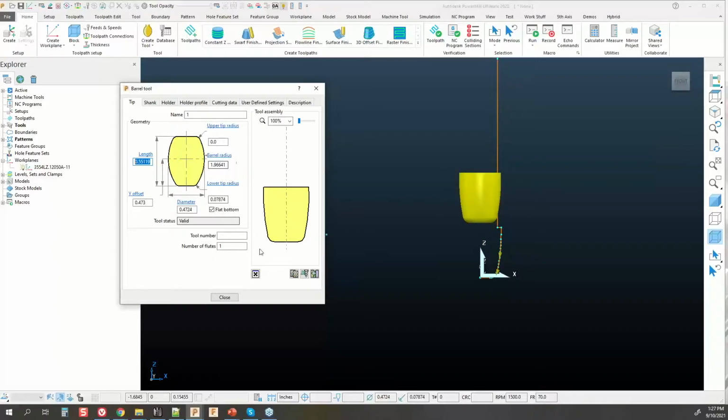All right, so this would be a successful barrel cutter, and it is a flat bottom cutter. If this does come to a point with a point radius, you untick that, you'll get a radius option with that. So different ways we could do that. Now, if this fails for any reason, like let's say you add that data, and for whatever reason, there's an angle to the tool, maybe it's a little bit steeper, that shifts that center point up above the length of the cutter, all right, that is when it's going to fail.